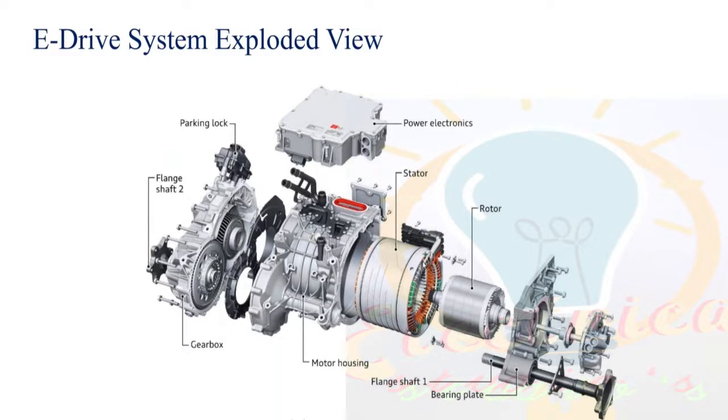To sense what? The main component that rotates here is the rotor. Stator is not going to rotate. So the rotor's position is what is very primary for the positioning, and we use the resolvers and encoders to determine the rotor position, flux angle that is generated there.